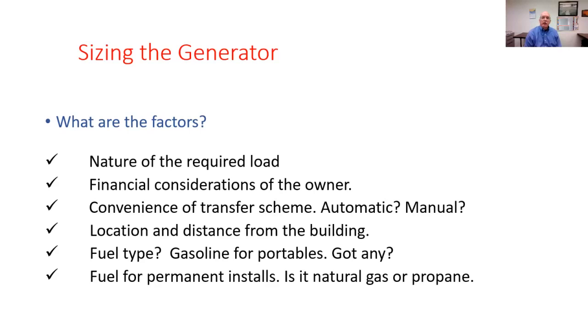Convenience of the transfer scheme. Do you want automatic or do you want manual? Well, I wasn't going to do anything less than automatic. I want my generator to turn on even if I'm not home. How about the location and the distance from the building? Well, the customer I talked to yesterday, she doesn't want the generator to be visible. She wants it hidden behind the pine trees 200 feet down on her property.